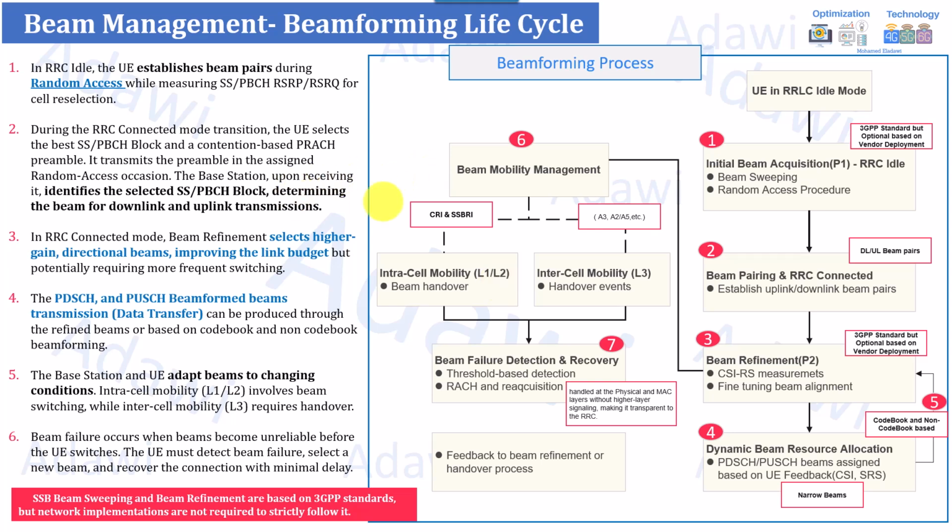Then moving to the next part, it's about beam failure detection and recovery. First of all, this will happen whenever, for example, assume you have beam switching from one CSI-RS beam to another, and this beam switching fails. So this can trigger a beam failure detection. This will be detected by the user. There is a beam failure. Also, I have a detailed explanation about that part.